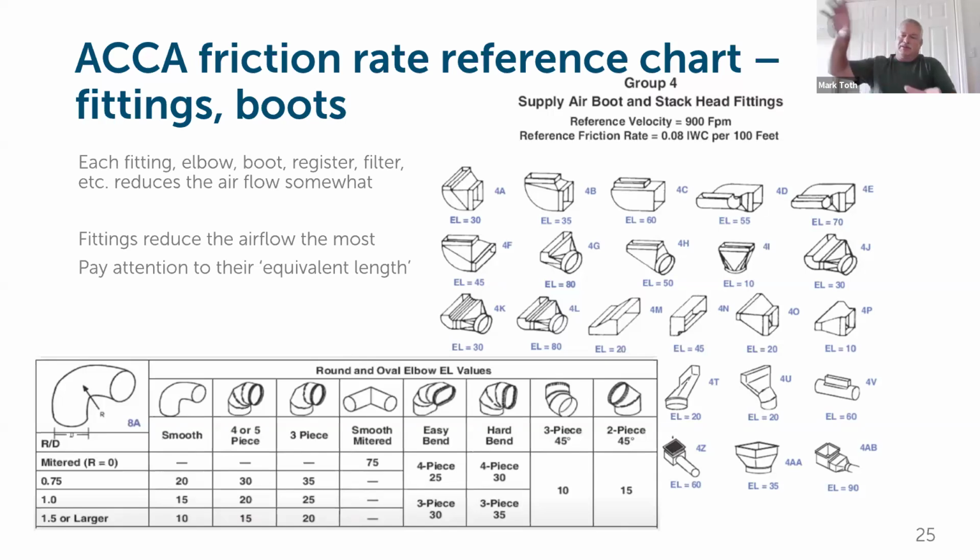In a normal system, a sheet metal elbow, the kind that adjusts a 90, is equal to about 15 feet of ductwork. A T is equal to 30 feet of ductwork. So putting a lot of fittings in your system really makes it a lot longer. You might have a very small area full of ductwork, but if it has 6 elbows and 2 T's in it, there's a lot of straight pipe measurement there, which can create a lot of friction for your fan.